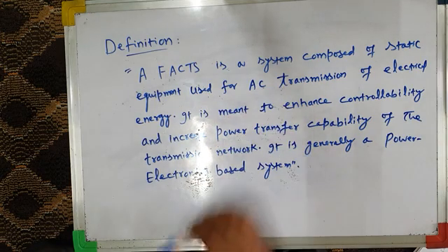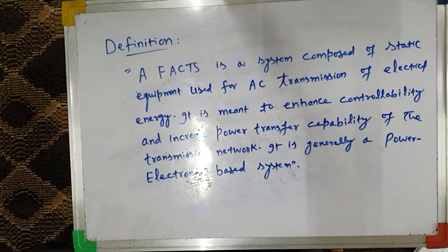So this is what FACTS is about. FACTS is nothing but static equipment, which is basically a power electronics based system that's used for AC transmission of electrical energy, and it is meant to enhance the controllability and increase the power transfer capability of the transmission network. So this is a concise definition of FACTS.